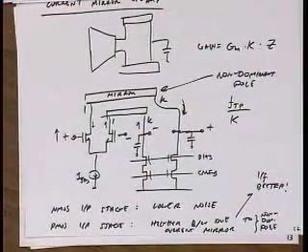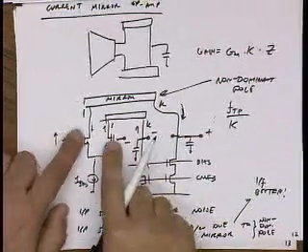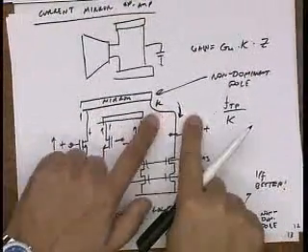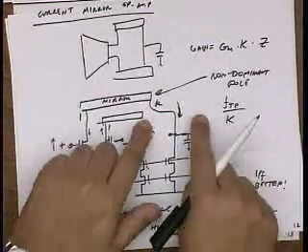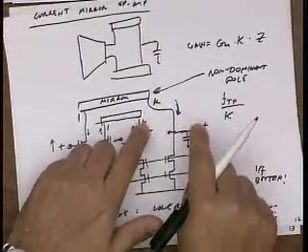Alright, and that's also similar to the considerations of a folded cascode, because in a folded cascode, this also feeds into a cascode PMOS stage, right? And that sets your non-dominant pole.